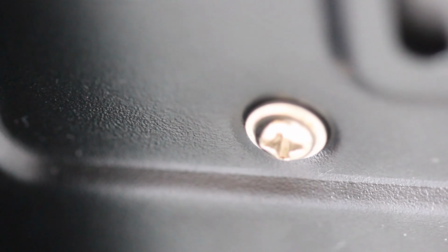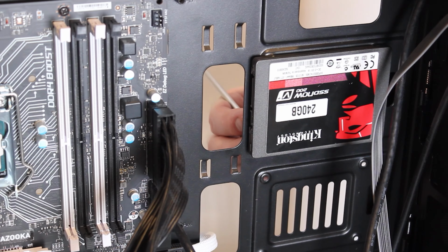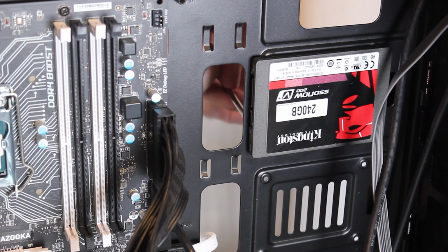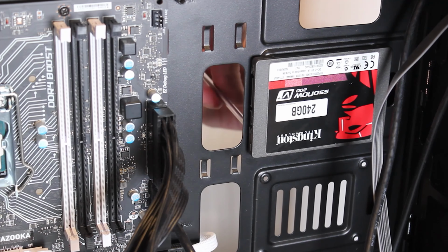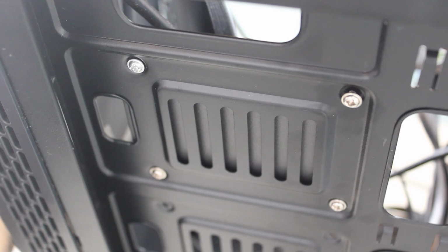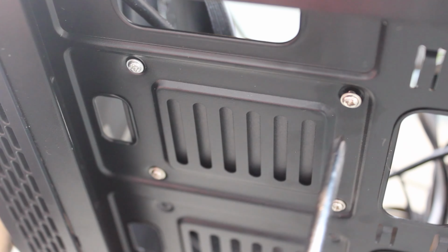I like to start with opposite screw holes first, as this tends to keep the storage device aligned better when installing, but it is not a problem if it lines up correctly. If it is not aligned with the screws, you will find that it is difficult to screw the screws in, and you risk stripping the threads of the screw holes if you screw them too tightly. Once complete, just check each screw to make sure they are screwed in correctly.